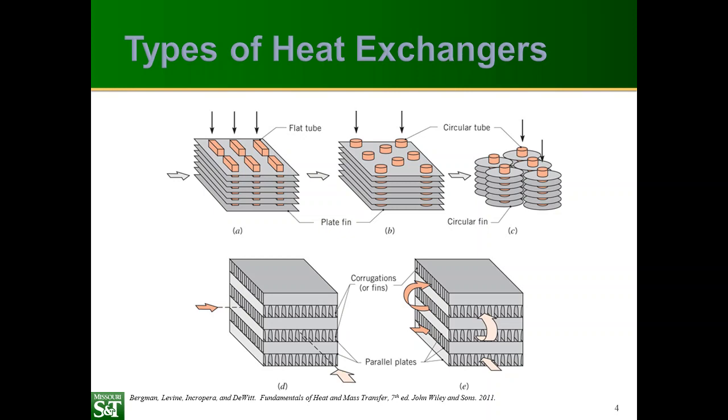There are many other types. The drawback to these is that you have a very large friction loss or head loss for the fluid as it flows through the heat exchanger. So this requires additional pumping power, which again is going to be more expensive than traditional heat exchangers for operation. They're also much more sensitive to fouling by corrosion and dirt and blockage of heat exchanger channels because the channels are so much smaller.